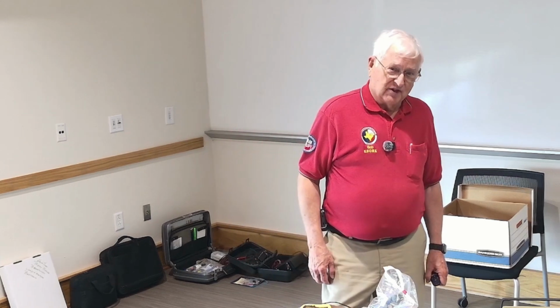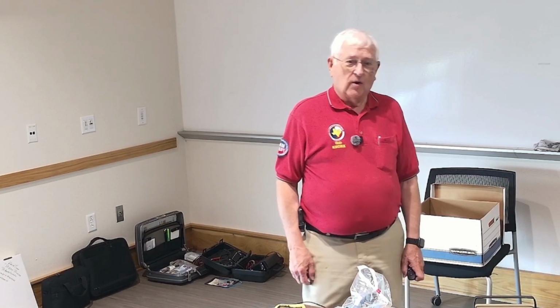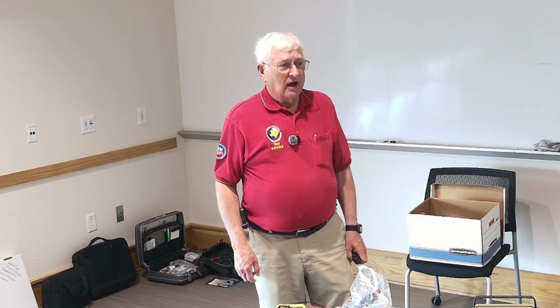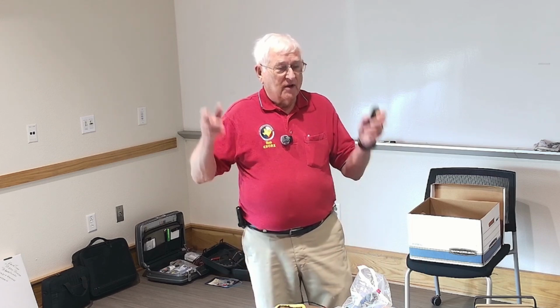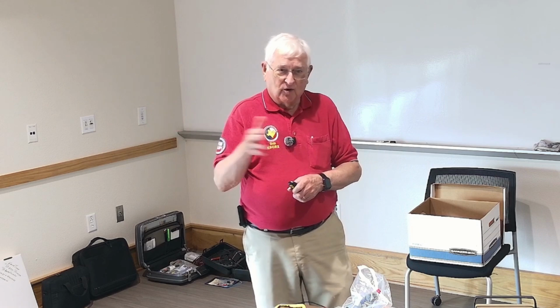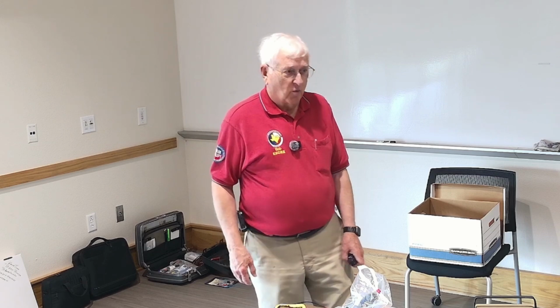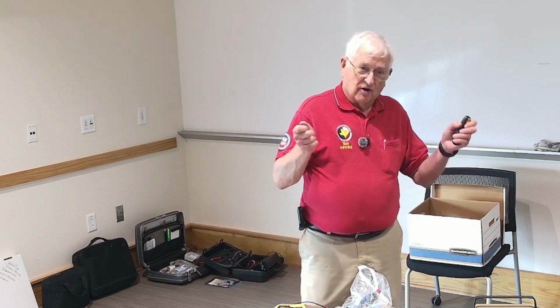Totally not. They tell you not to touch it. There's a reason for that. Weird things happen between the radio, down the coax, and into the antenna. Even though that radio is running on only 12 volts, the RF coming out the ends or the middle of the antenna, depending on where you tap it, can be several thousand volts. It really can. It's like a transformer action. It really gets up there. That's why you get an RF burn from it.